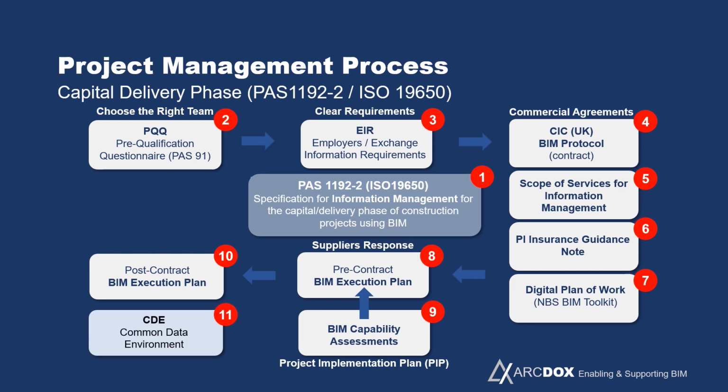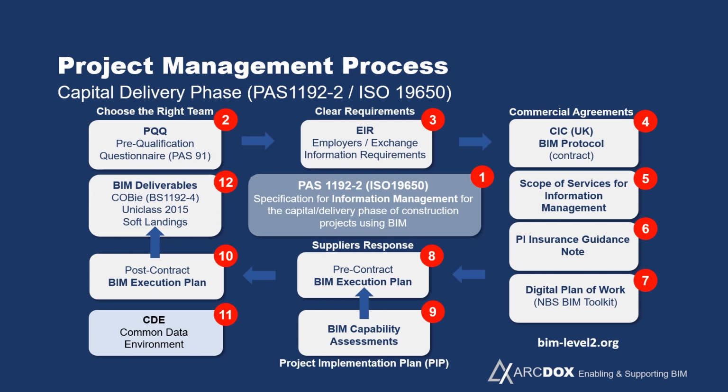For the project, a common data environment has to be put in place. So it's a digital repository where all the digital files will be held and managed, and we'll describe that in more detail. And at the end of this process, there will be a deliverable. In other words, the project team will deliver a digital version of the building, which will include operational data, or COBie.